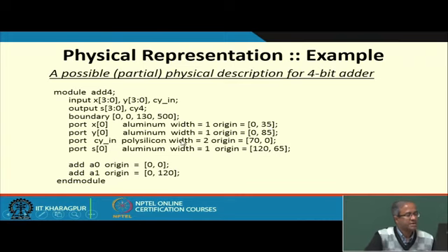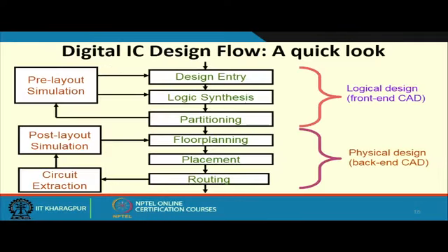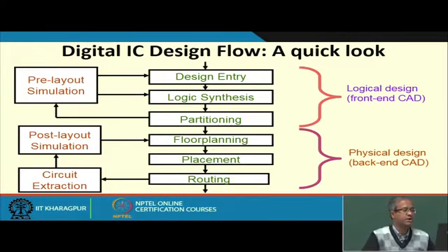So, in this way you have some primitives for the ports, the boxes, lines, everything, where you can exactly specify which layer it is running on, what is its starting coordinate and what is its size. In this way you can generate the final layout as well. This will finally be used for fabricating the chip. So, I think we have got a fairly good idea.